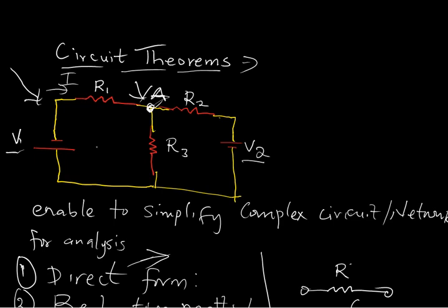It's a junction because current that reaches this point A, as it flows from one of these sources, will branch. It will divide into two branches. So this part where resistor R2 is connected is a branch, and the part through which resistor R2 is connected is a branch. So this junction, or node, is the point where the current divides into branches.